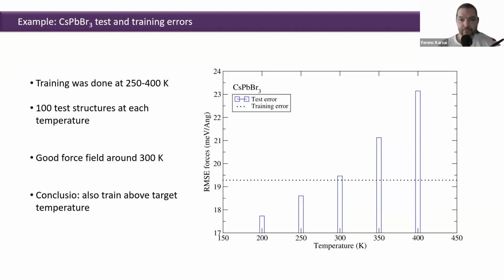I would just check within these calculations the quantities that need to be conserved, for example, if you run an NVE, the energy, or the pressure in an NPT, or the temperature on average.